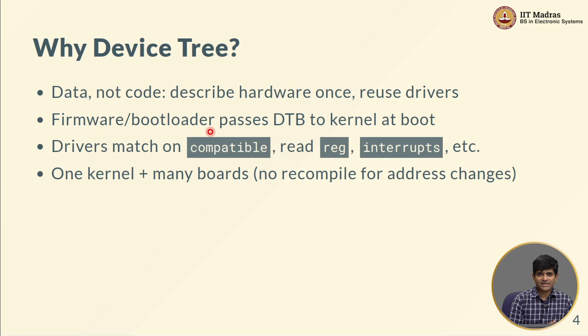The way that it is done in practice is, there is what's called a first stage bootloader, whose job is to have just enough device drivers to be able to read from the SD card, take some data, put it into an appropriate location in memory, the equivalent of the loadelf command that we gave in Renode, and then jump to that particular location and start executing. The good thing is, because we now have the small piece of software which acts as a so-called bootloader, it can also read in a device tree and put it in a specific location in the memory once again, and the kernel can then pick it up from there, right.